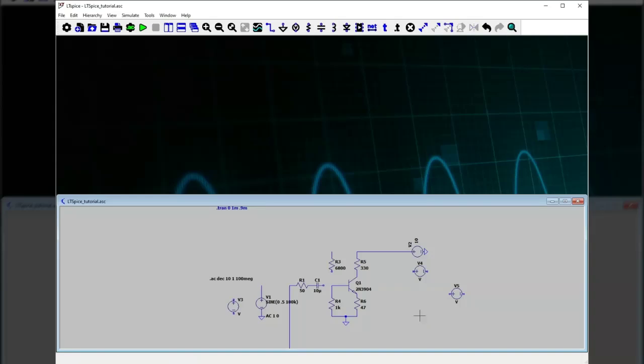But now, what about the resistors and capacitors and things? Well, for resistors, you can come right to the top of your screen. Resistors and capacitors and inductors, you come right up to the top of the screen and get R, C, and L, and ground. Your grounds, you need some grounds, so those are right at the top of the screen also. Or you can go to Edit Components. And there would be a way to select resistors and capacitors, and then you place them.